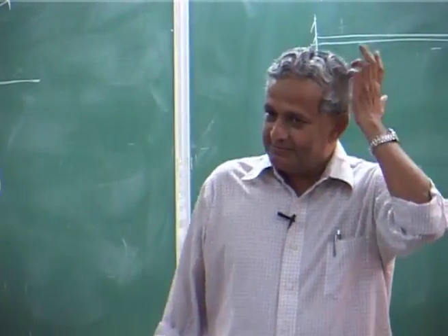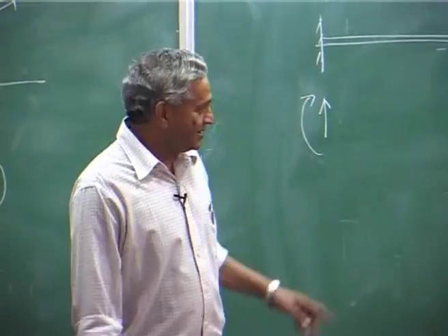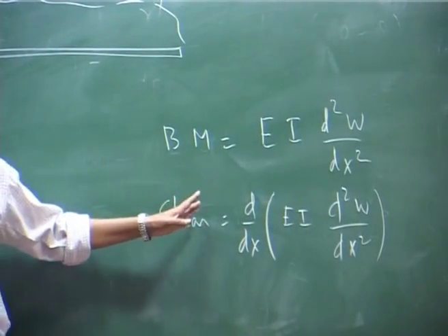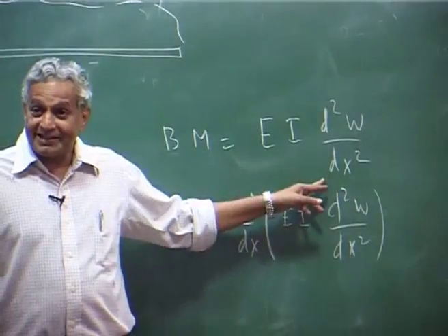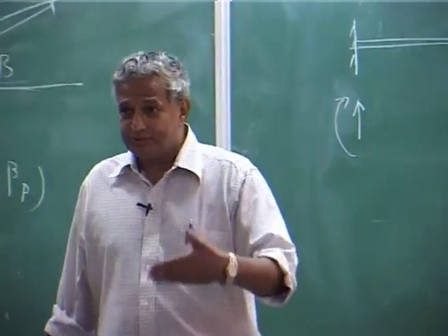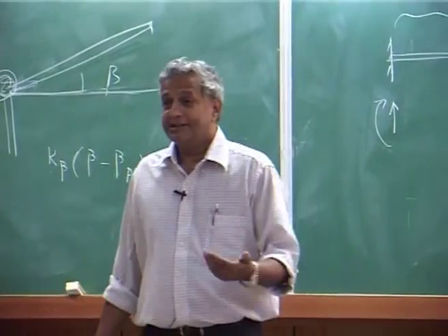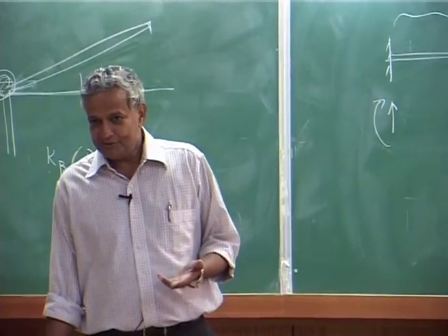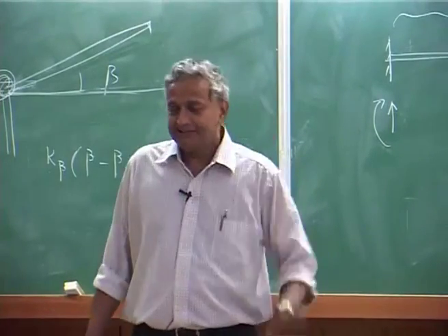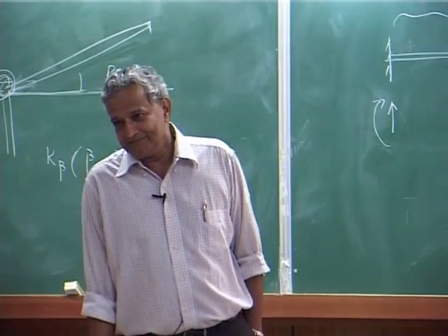So usually we do not calculate bending moment and shear by this approach, for the simple reason that you are taking secondary quantities, and all approximate, numerically. Whenever you do differentiation, you may have error. So when you want to get the loads, you simply integrate the aerodynamic and inertia loads.